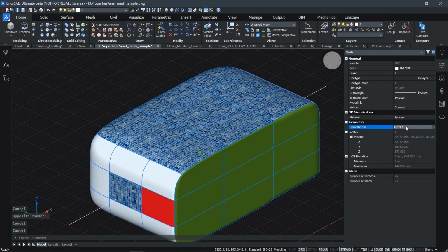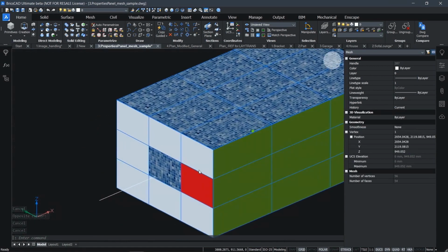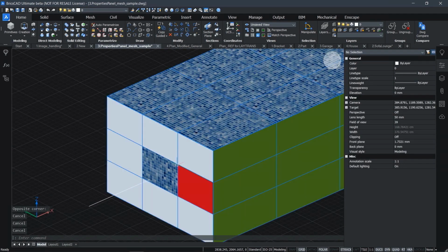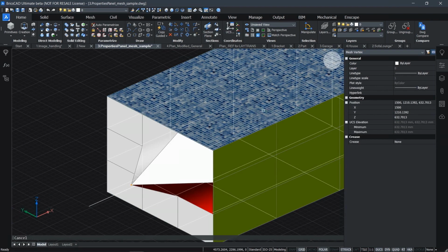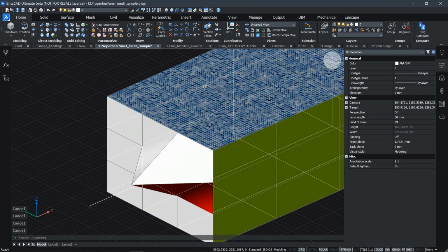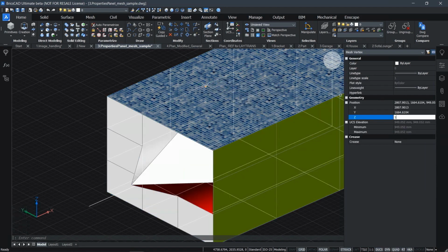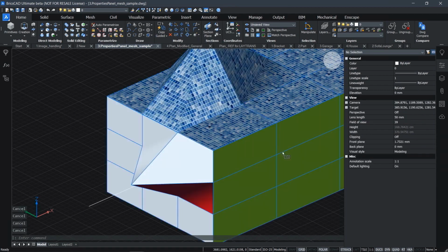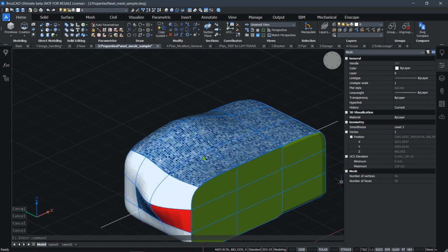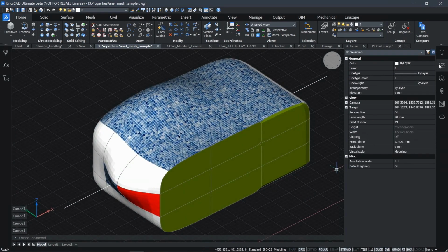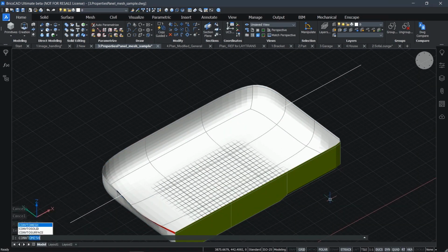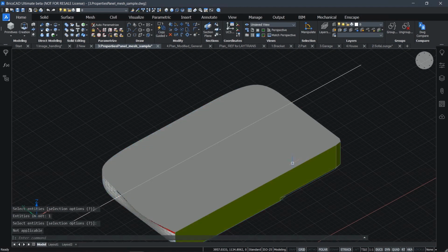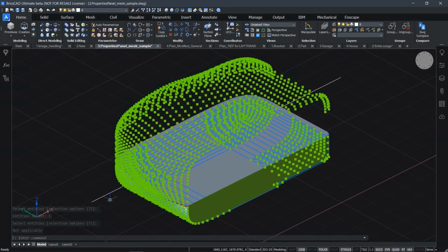And let's go a little bit crazy even. Let's set the smoothness property to 0, to none, and pull out a point, and at the top we'll pull out another point, and then we'll switch on the smoothness again, and we've completely remodeled this imported thing in a couple of seconds. Okay, but at BricsCAD, we love our solids. So this is only a mesh now. Well, we simply convert it to a solid. And once you've done that, we have the direct modeling tools to further manipulate this object.